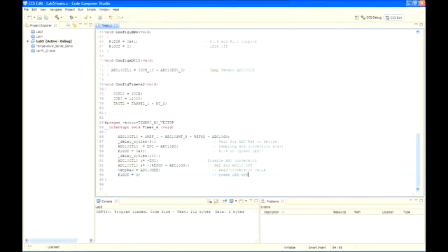So almost everything's in place for the first interrupt to occur. In order for the second, third, fourth, and so on to occur at 1 second intervals, two things need to happen. The interrupt flag has to be cleared. Well, that's automatic. The CCR 0 has to be set 12,000 cycles into the future. So add the following as the last line in the interrupt service routine. CCR 0 plus equals 12,000.